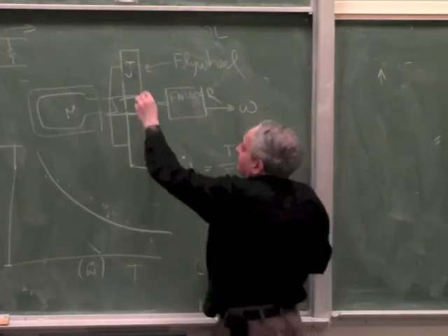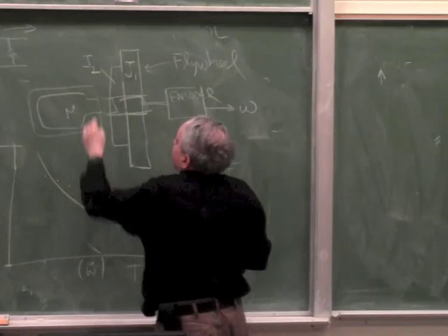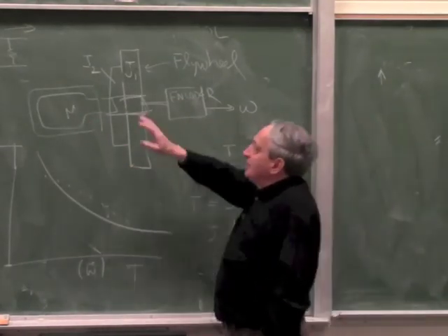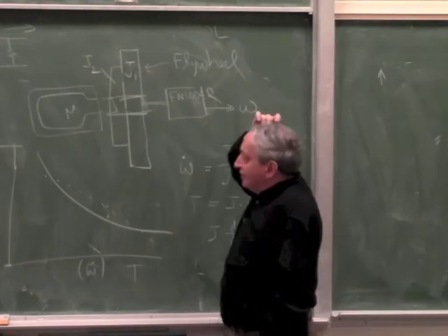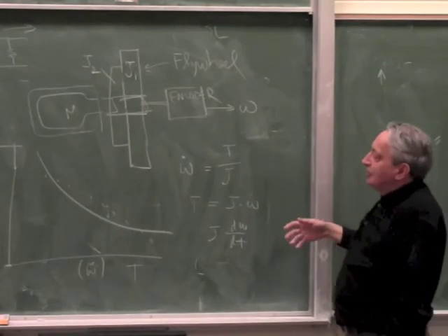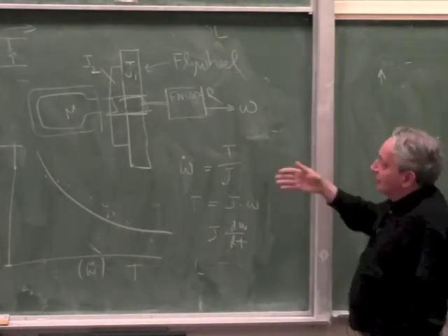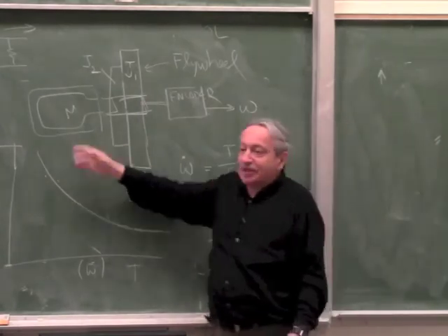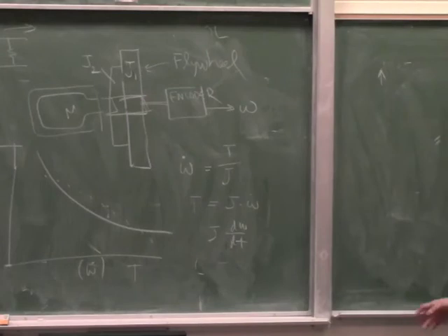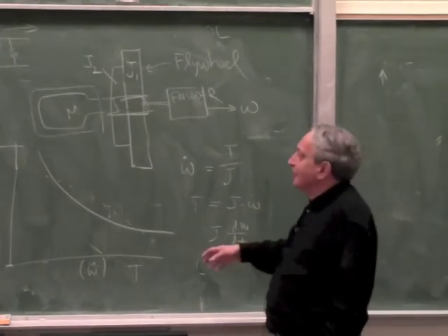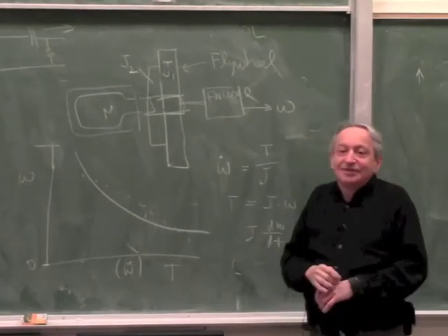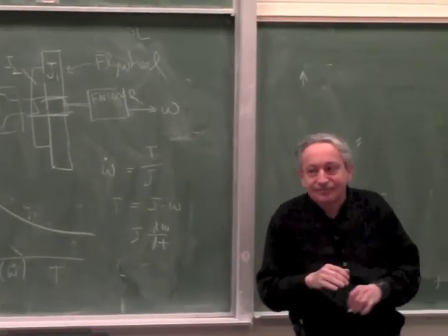So it's the same as adding another one. Okay. So you say this is J1, you add J2, and J2 could be the motor inertia. Now, in this case J2 is not known. However, if you do that, you'll get another plot, and between the two plots you can calculate what the internal J is. Okay? So basically the most elegant way to plot torque versus omega is just let the motor start and just monitor the speed. Okay? Good.